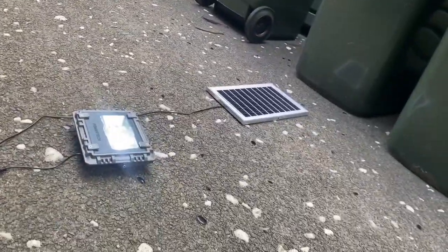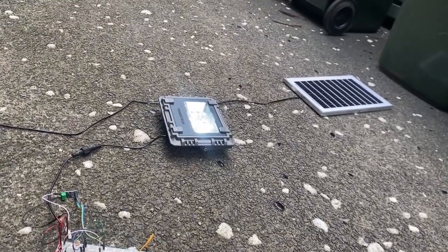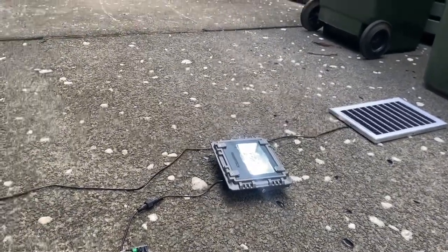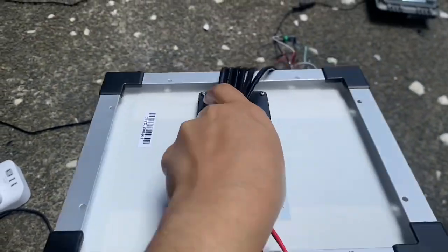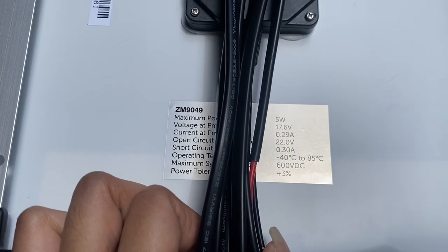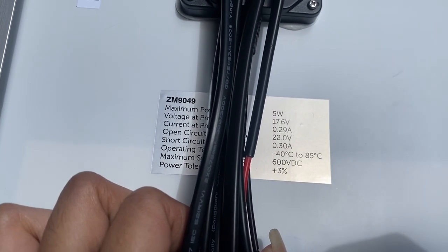Okay, so next I'm gonna explain the technical difficulties that we faced along the way. First of all, we were not gonna use this same solar panel and floodlight, but instead a smaller solar panel, which is technically cheaper than this one, and we used an LED to light it up. But unfortunately, the first solar panel, hang on a sec. All right, this is the original solar panel that we were about to use. We can read from the description here: the maximum power is 5 watts with the maximum voltage at 17.6 volts, but that would only make a current at Pmax of 0.29 amps, and that is actually way too small.